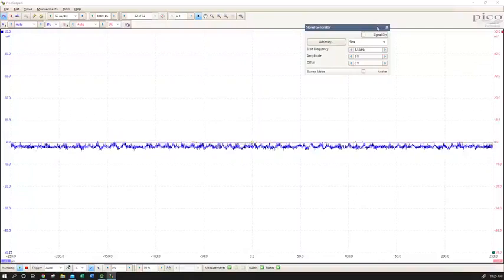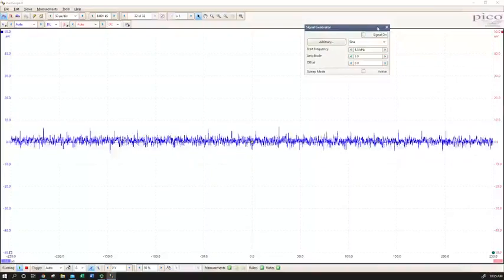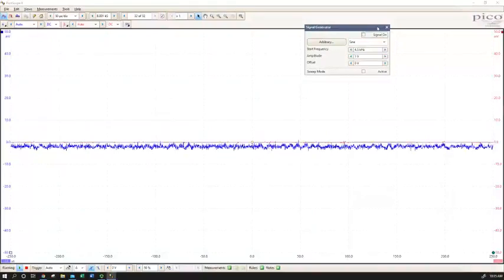I just found that by moving the capacitor value, I was able to shift the F resonance such that I was able to display it more clearly with my spectrum analyzer and show it a little bit easier with my scope. Obviously, I can change F resonance, or FC, for the same value of inductance.